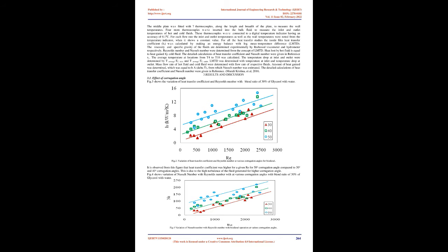But when one of the fluids was very viscous, e.g. glycerol, the temperatures of both fluids were significantly higher, while the effectiveness can be higher or lower than the value predicted by the classic relations. In particular, for cases with a very viscous hot fluid, the effectiveness may be even higher than unity.